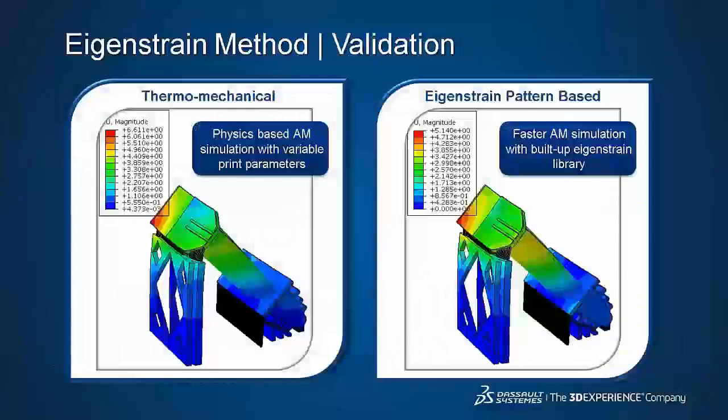So those Eigenstrains, we went ahead and used them. You apply the calibrated Eigenstrains and use them for this realistic aerospace turbine blade model. The results from thermomechanical and Eigenstrain methods prove the effective use of Eigenstrain methods for process simulation for realistic and complex parts. So with the growing Eigenstrain library, the Eigenstrain approach can become handy for continued use as users move forward further in additive manufacturing.